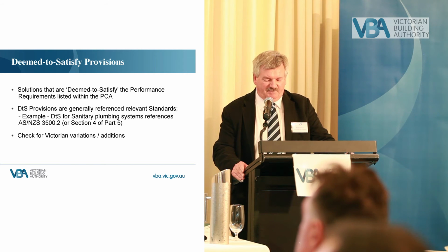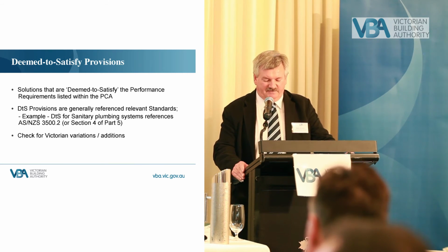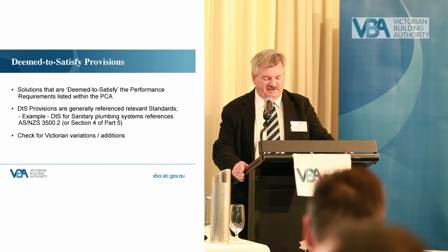To use the sample performance requirement from the previous slide, which related to the design of the sanitary system, the DTS provisions refer to AS 3500 Part 2, or the housing section of Section 4 of Part 5 of AS 3500. Some states and territories have varied how the PCA is complied with, and you should always check to see if there's a variation or addition to the DTS.